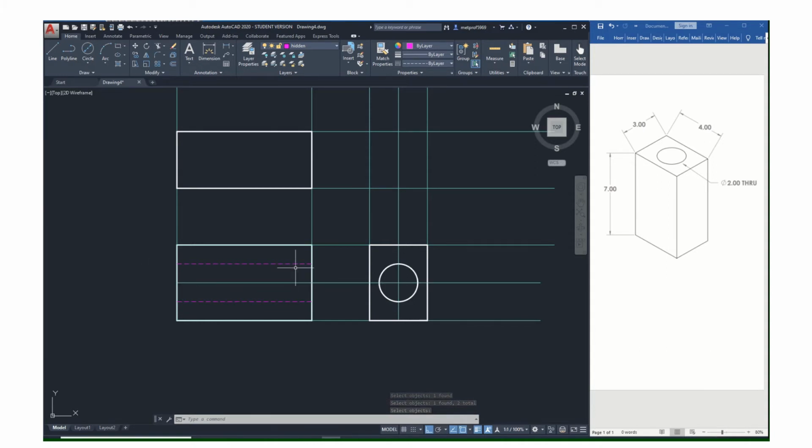Okay, so again, that shows the top of that hole and the bottom of the hole. The fact that they go from edge to edge shows you that the hole goes all the way through. So without any writing saying that the hole goes through, you can see it visually. Now, hidden lines always stop at the edge of the part. They can't go beyond. It wouldn't make any sense. This is just empty space. Why would you have lines extending out in there telling you that something is hidden?